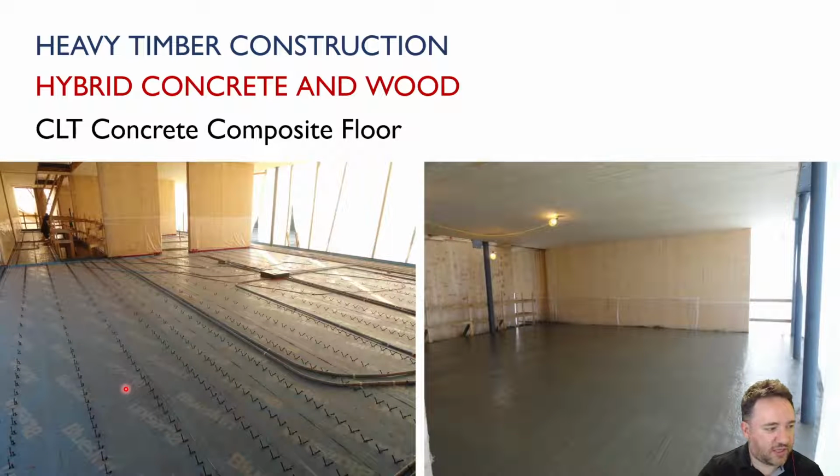Okay, here we have another thing that's being done and researched a lot these days, which is to combine CLT floors with a concrete topping. The reason for this is primarily stiffness and also acoustics, because one of the problems that has been found with CLT floors is that since they're very stiff and light, they can transmit sound, for example walking sounds, through. Adding the weight of concrete and that material on top can help to mitigate that problem.